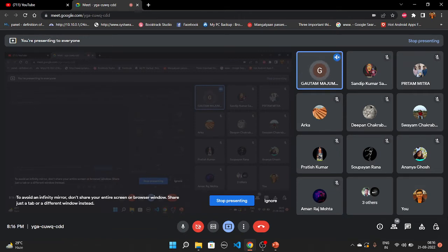Mostly for a taper, the bigger diameter and smaller diameter will be given if it is a cylindrical one, and the standard taper angle or the taper per inch or taper per foot will be given to you. That table will give you how many tapers there are in that size. So Morse taper, Jarno taper, Jacob taper. Please see the classification of the tapers and where they are used in which machine tool. Also, most importantly, before you go to the measurement, what are the other things that you should look into in the taper? I think that should also be discussed in the class. In the meantime, there are different taper turning methods in lathe.